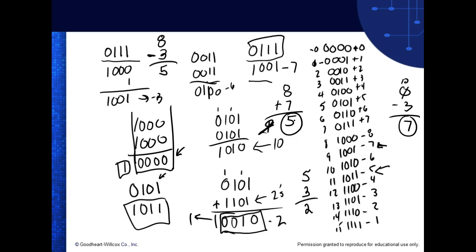If I add 2 numbers together and get the wrong sign, that's an overflow, not a carry. There's a difference. An overflow indicates you exceeded the range of the signed number. A carry means you exceeded the range of the register.